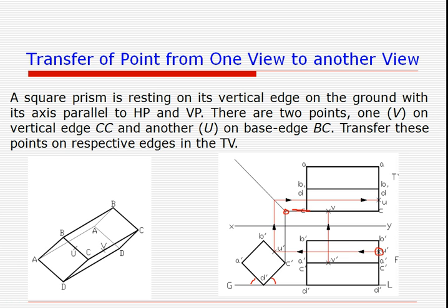the extreme points like this. From the extreme point like this, you draw the 45-degree line, and on that 45-degree line you will have this, then vertical, and then again horizontal. Then you know that it is on this B dash C dash. On B dash C dash itself you should get it transferred, or in the BC, which is in the top view, you will get it transferred. That is how you do the transfer of points in a number of situations. So thank you.